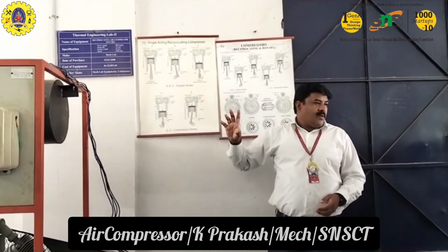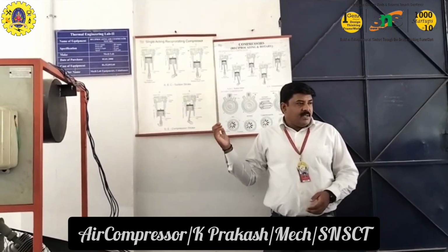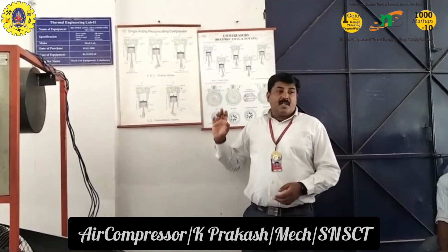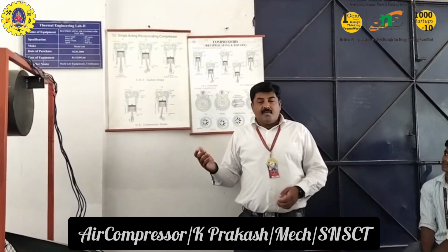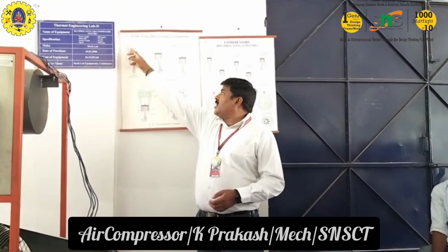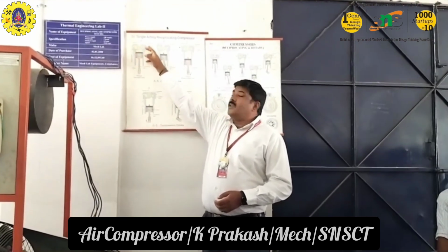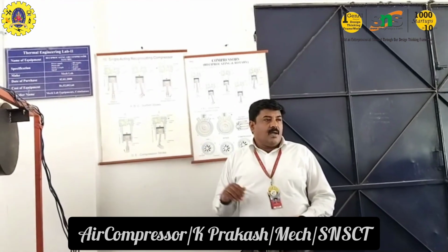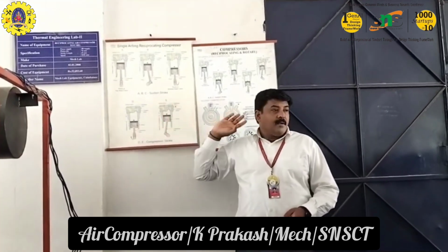So this is the working of a reciprocating compressor. Are you clear with this working? This is the single acting reciprocating compressor. Why am I telling you single acting? Single acting means the air is taken inside, compressed, and delivered on the same side of the piston or the cylinder. This is why it is called a single acting reciprocating compressor.